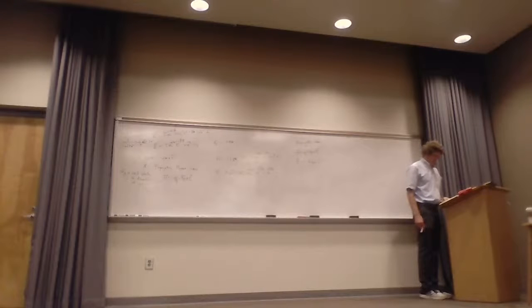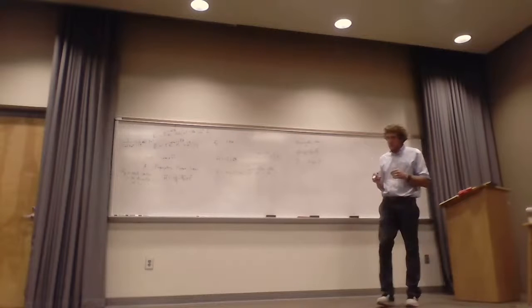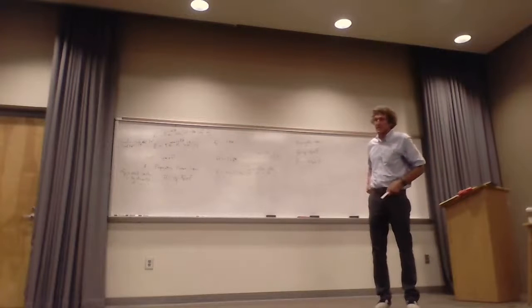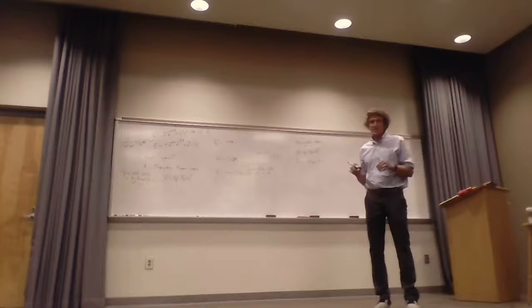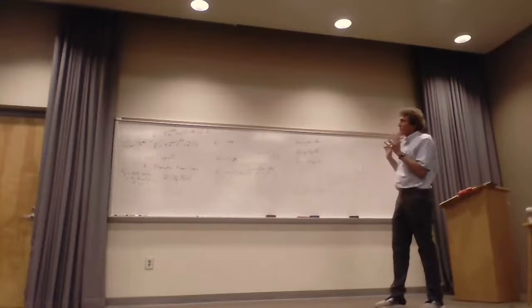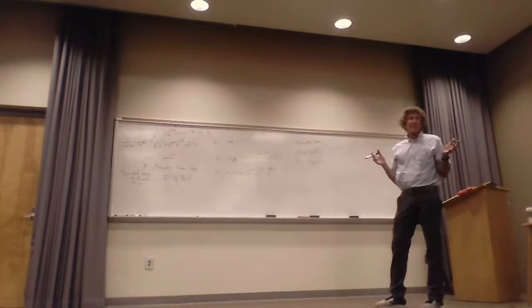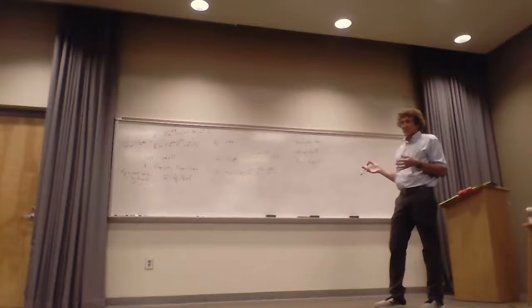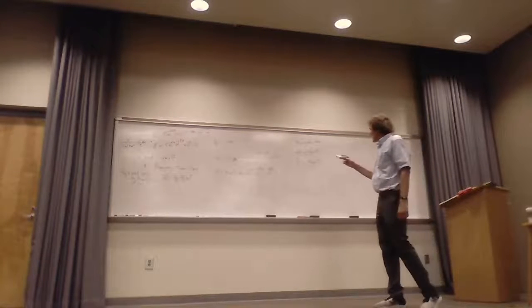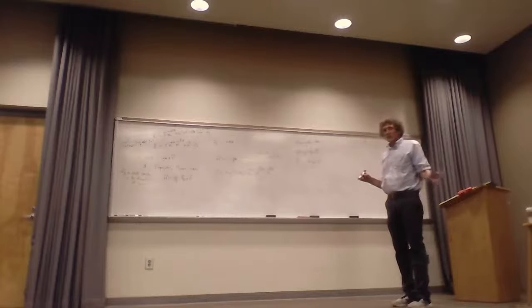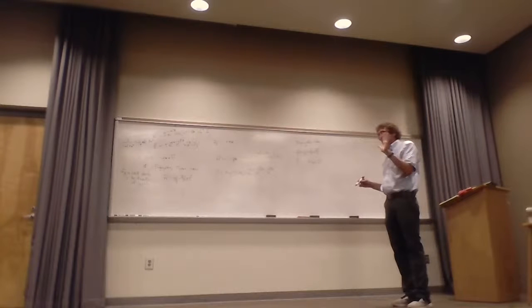Again, make sure you put down plane waves. I want to make sure you say that. It's true for spherical waves too, to an extent, but it's not exact. I don't think it's exact. That's the reason to take a curl. If you're ever worried about getting an exact value for H, take the curl of E. And if you want the exact value for E, take the curl of H. Then you've got it; mathematically, you're going to be exact. All right, now those two are good. But when we have a wave propagating in space, there's a power density.